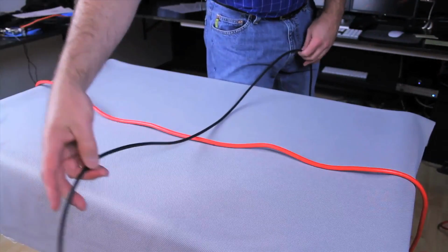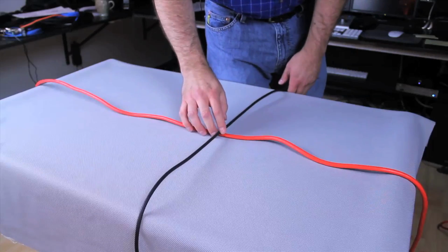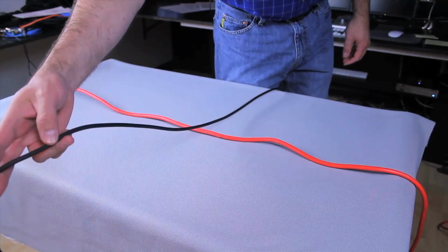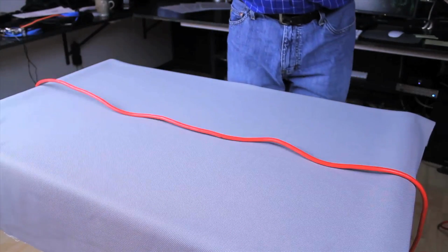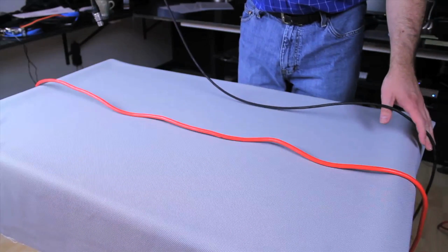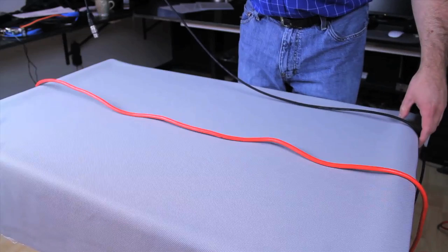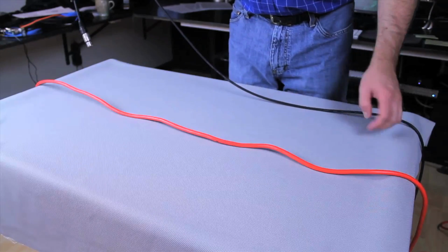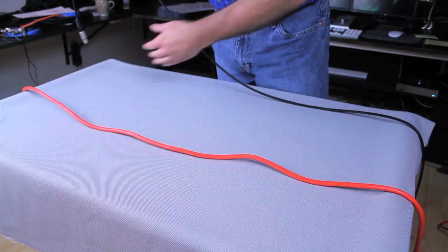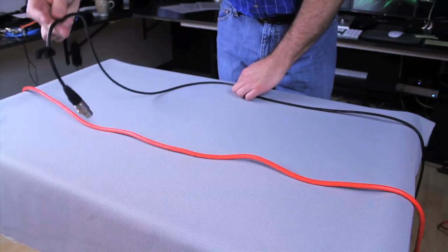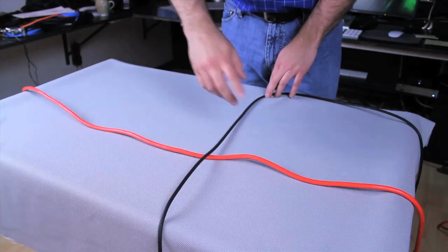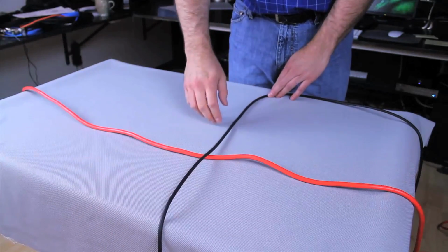You come at perpendicular to the power cord this way. And another solution to a problem is you need to run your mic cable along this for a while, but you need to get across. Just again, maintain that 1 foot rule, and then cross over at 90 degrees at some point, and then go ahead and run onto your source.